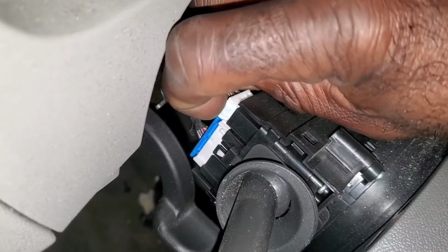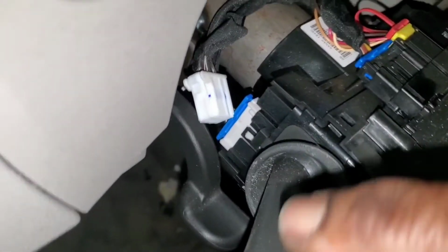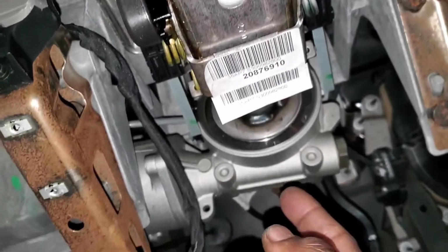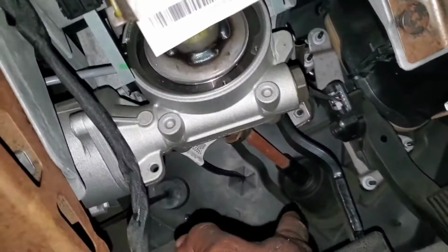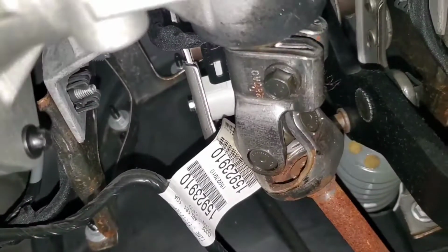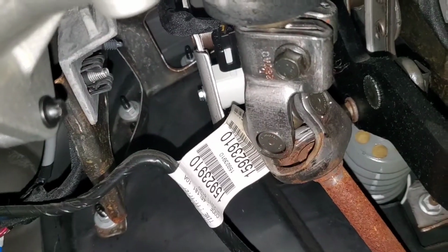But I do know that one of the important ones that I don't want to fight later is the actual torque sensor connector down there. So let's take a look at that. So the steering column is this whole contraption from here on back, okay? And the bolt that gets replaced is under there. So remove that boot, and I think it's under there. Or is it right here? I can't really. Oh, there it is. Sorry. It's right here. So take that bolt out. That's the one that gets replaced.